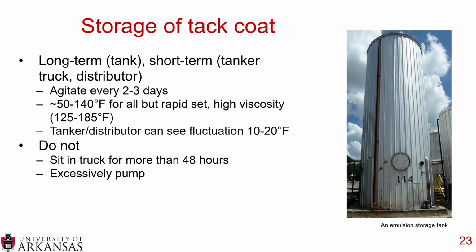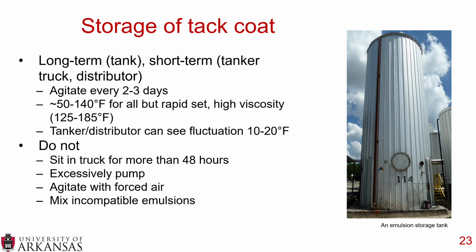You also do not want to excessively pump your asphalt emulsion. So you don't want to pump it into a truck, off of a truck, back into a tank, back into a truck, back into a tank, and so on. Excessively pumping it does degrade the asphalt emulsion. You do not want to agitate it with forced air. You want to have mechanical stirrers to stir your asphalt emulsion.